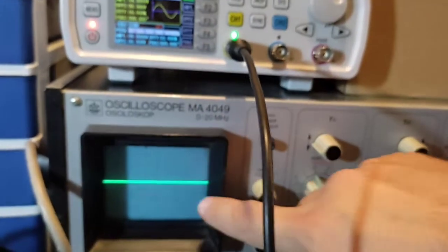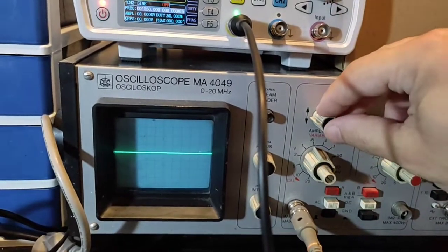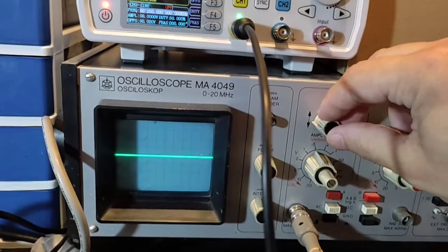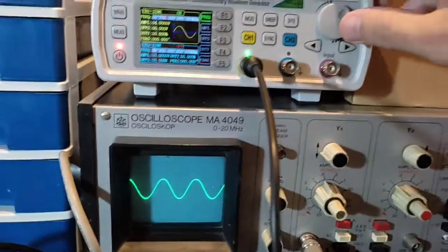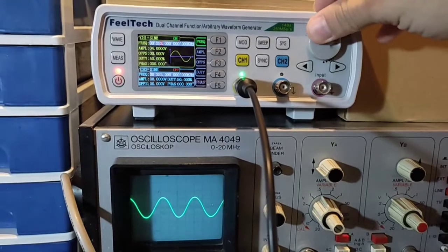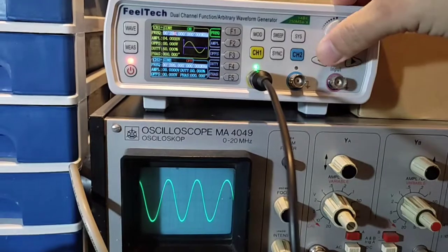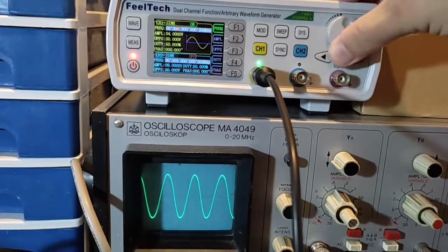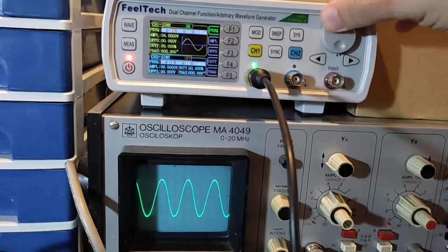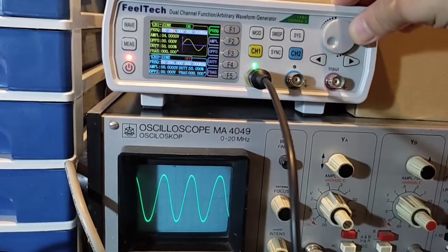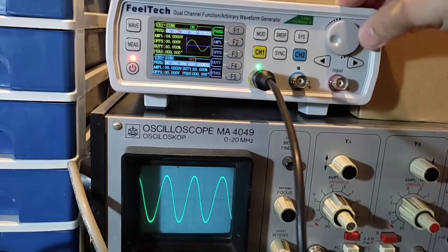It's an old analog oscilloscope, so it changed its values during the time. Okay, now that works okay, and I'll start increasing. We can see that the amplitude is rising. We'll have a peak at one point, and there it is. As I increase the frequency, it goes down. So this is somewhere where we have the resonant frequency.